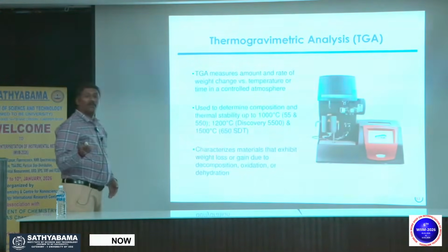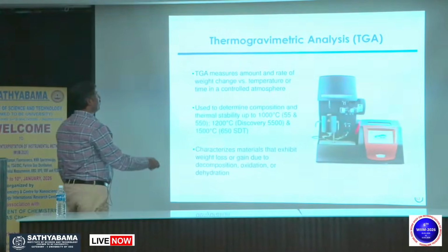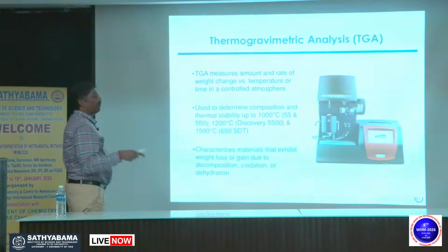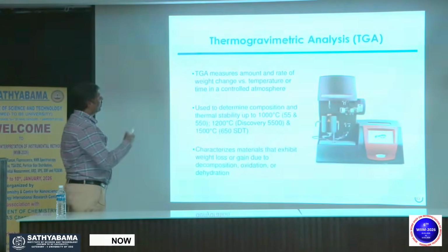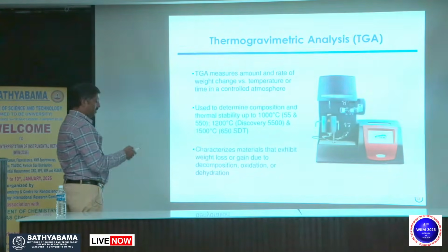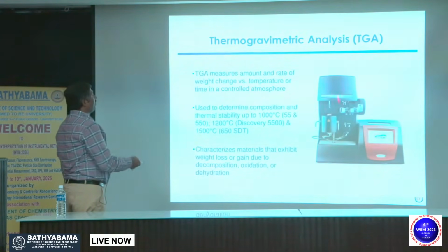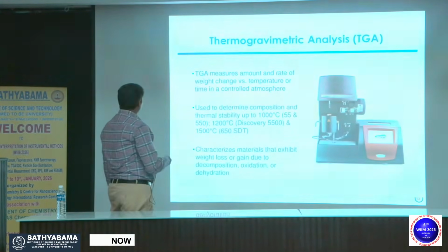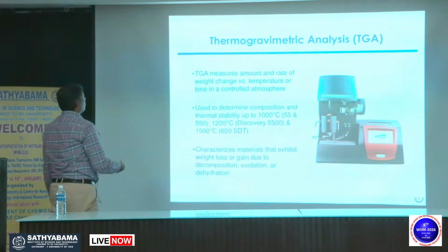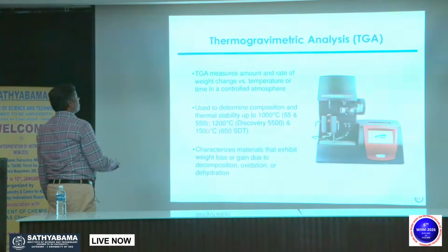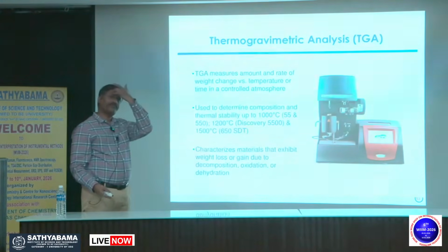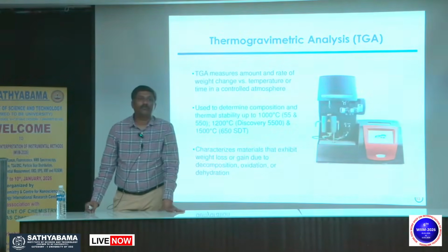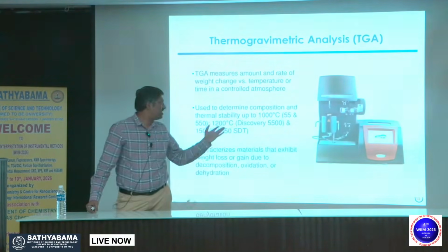So this is how it looks. I am not promoting TA, but this is how one of the instruments looks, where you have the sample inside. You have an inlet and outlet for your water bath or oil bath to maintain the temperature, and you can see the results here, and you can apply external pressure if you want. This instrument can run up to 1200 or 1500 degrees Celsius from room temperature. The sample requirement is 50 milligrams. The cost is close to 60-70 lakhs.